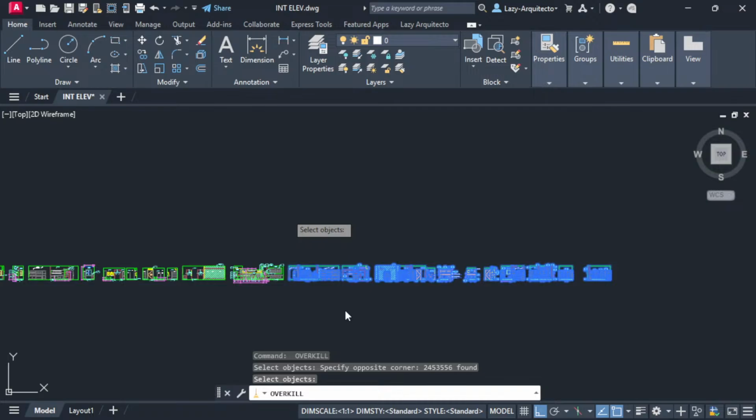Searching for duplicate objects. And that's the problem of exporting drawings from other programs such as Revit, AutoCAD Architecture, and so on. Their blocks might have edges and tiny lines forming those edges, and we need to optimize it somehow here in AutoCAD, and that's what we're doing today.